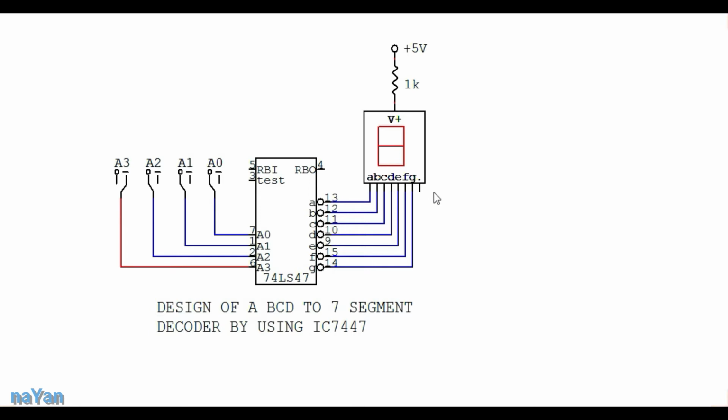So to test whether our 7 segment display is okay or not, we can just connect the 7 segment display with our IC and set input 8 so that we can see an 8 formation. If it gives 8, which means all the LED segments are proper and glowing.